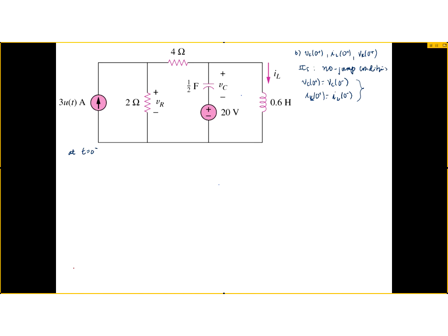How do you not forget that? When you're removing a current source, you want to make the IS 0. The current has to go to 0. What element has 0 current? An open circuit. Does that make sense? When you're removing a voltage source, you want to make the VS 0. What element has 0 voltage? A short. I think at one point you just memorized it, and when you just memorize something, it's as easy to unmemorize it. So try to put some logic.